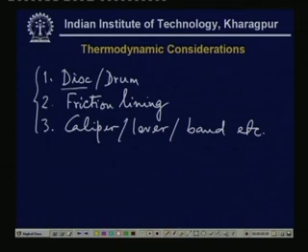So, what we do is make the thermodynamic analysis of that part which is mostly responsible for the temperature rise. For a disc type and sector type brake braking pad, it is found that the friction material is the most important factor in the thermodynamics. That is, this is the main source of heat generation. Of course, it is expected that the friction force will dissipate the energy in the form of heat. So, therefore, it is the friction material which is to be considered and which gets affected most by the heat generation. Now, the procedure for thermodynamic analysis is something like this.